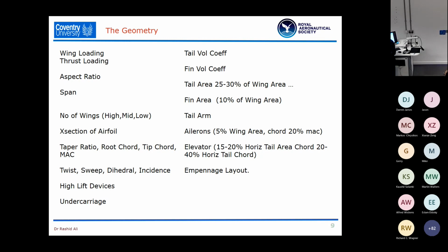So it's an eVTOL biplane. So we consider lots of interesting combinations. Again, how many wings you have, whether it is going to be a high wing aircraft, mid wing aircraft, low wing aircraft, that again has serious design implications. For example, low wing aircraft are a joy to land, or not as the case may be, especially if they come into ground effect, or the high wing aircraft do a positive landing depending on how you flare them.